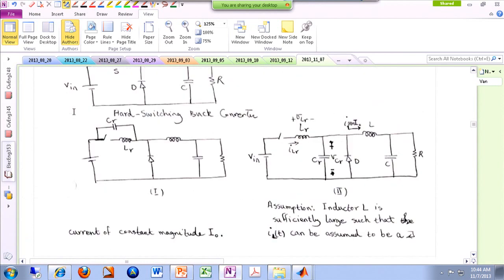which is basically this topology. As you can see, it is this Buck topology. So we have one switch, one diode, the inductor is over here, the cap is over here, but in addition to the components that we have seen before, now we are using a little bit of a resonating inductor here and a little bit of a resonating capacitor over here. So by adding these two components, things are going to get way complicated, but we are going to achieve, for instance, the ZCS, the zero current switching that we wanted to achieve.